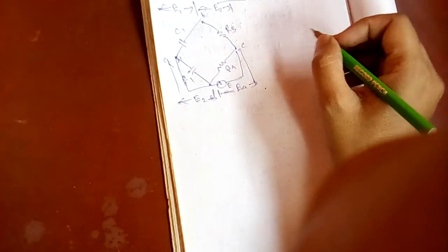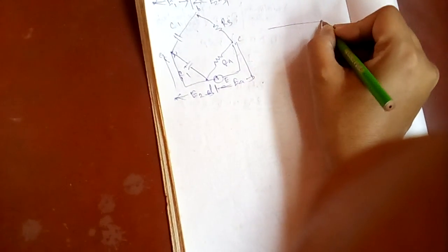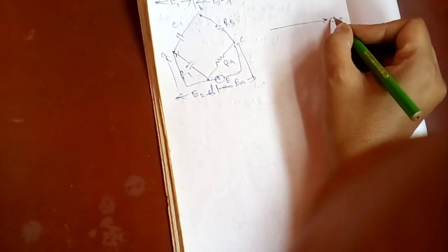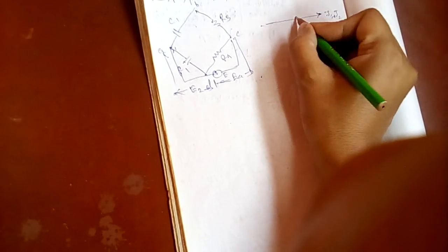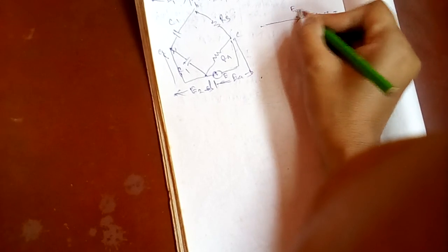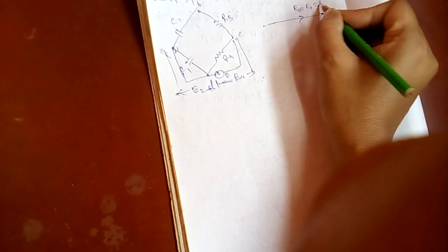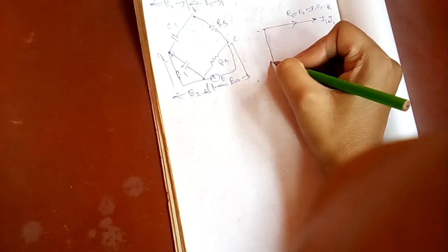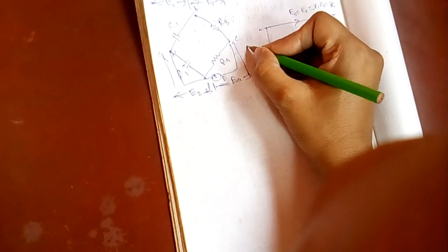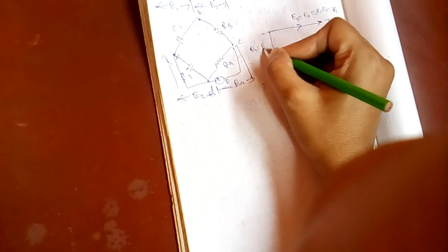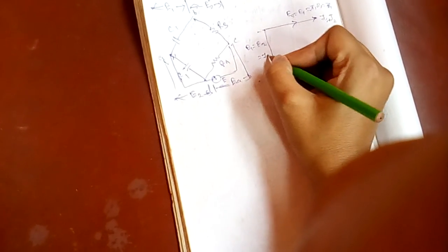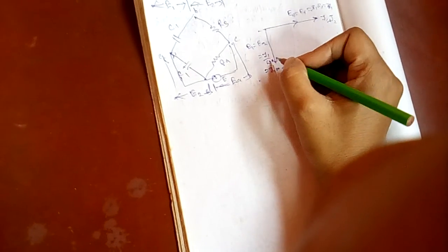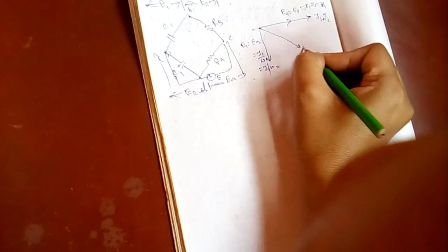So if we draw the phasor diagram of it, first of all I1 and I2 are in phase, and in the direction of E3 and E4, I1 R3 is equal to I2 R4, and the capacitor voltage is lagging 90 degrees. So E1 is equal to E2, which is I1 by omega C1 equal to I2 by omega C2. So if we take the resultant E,